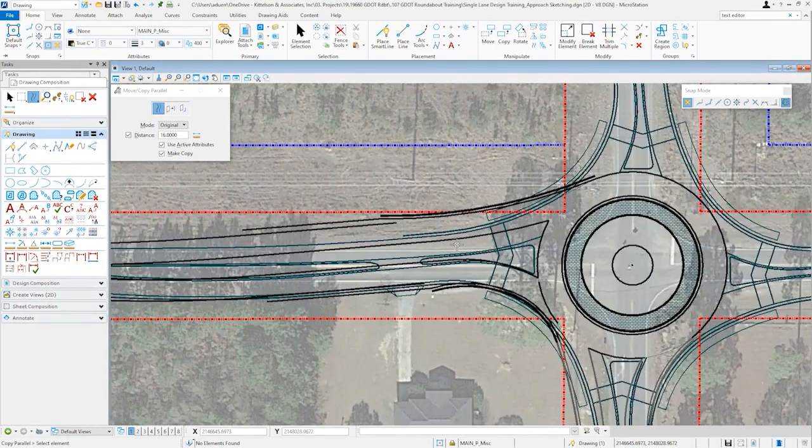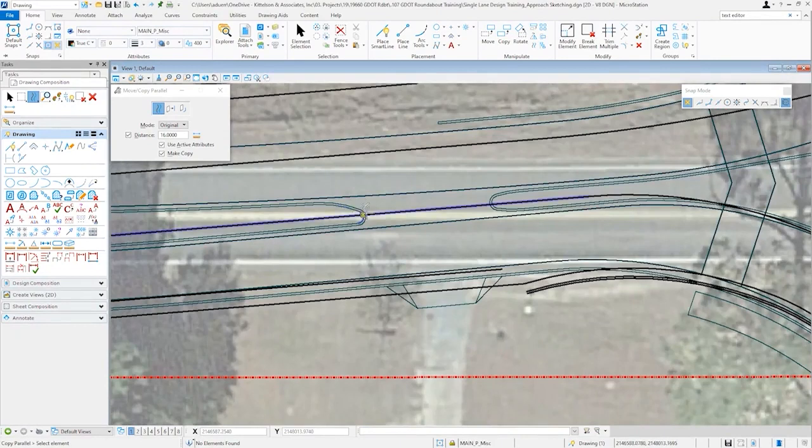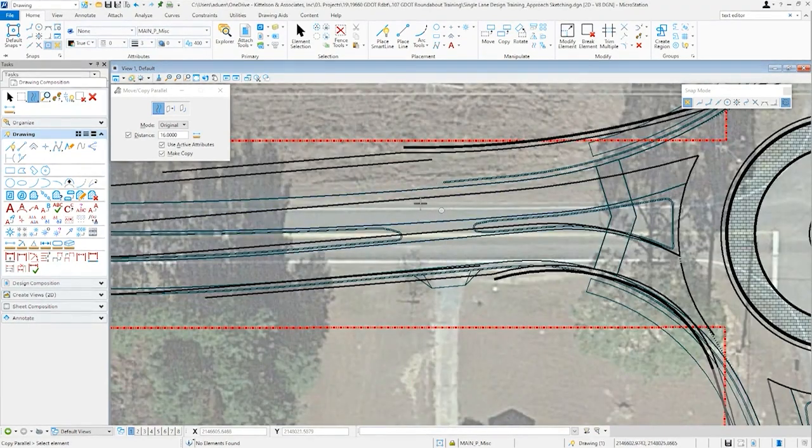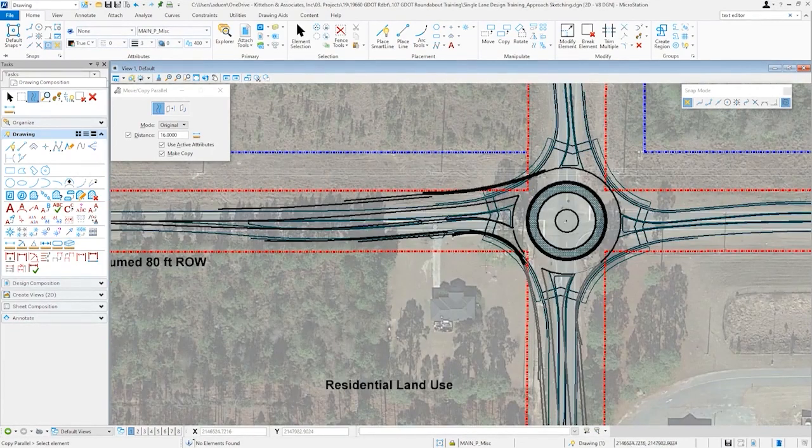And just a point there is that this is a residential house and they have a driveway. And if I zoom in, you can see the driveway break in the splitter island. And there a 15-foot wide median or splitter island in that area would be pretty wide for someone trying to turn in and out. So there is some benefit to narrowing it up. It helps make it easier to get in and out of that driveway. It also may have been a practical design consideration trying to reduce the amount of widening or construction costs.